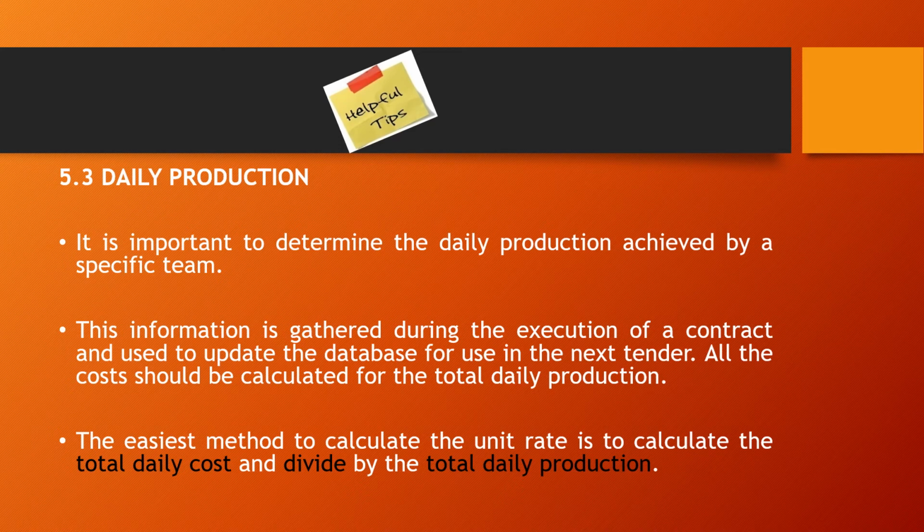Say the trench is 800 millimeter wide, and the TLB does say 150 meters a day excavation, and say 600 deep. You have to have all that information. You have to write it down and say, okay, typically on a day, in these conditions, this is how much excavation we're going to be doing, because that is what you're going to be using in pricing the next job.